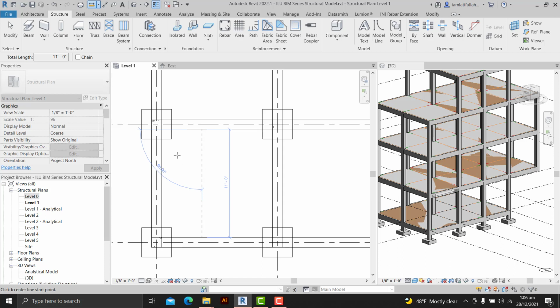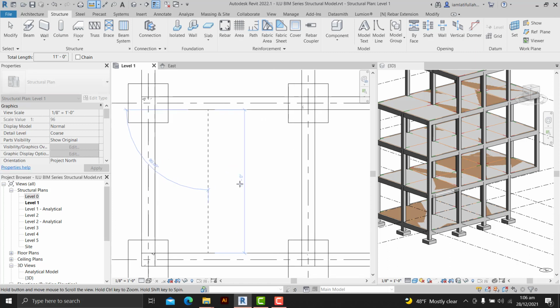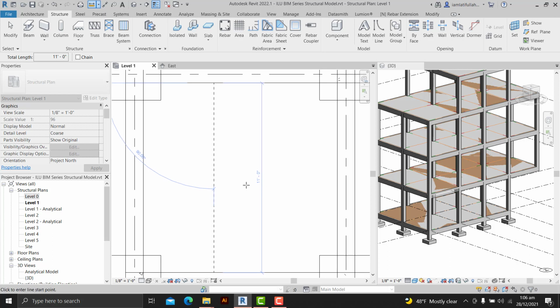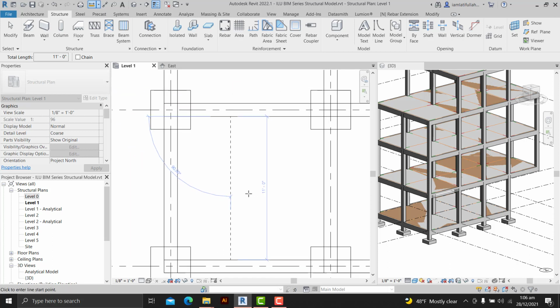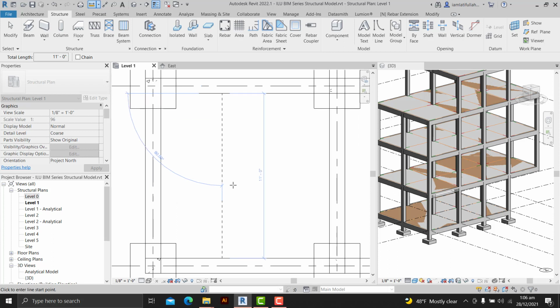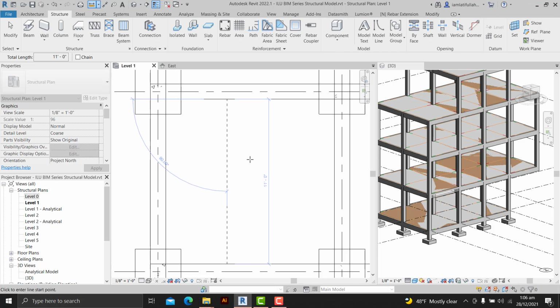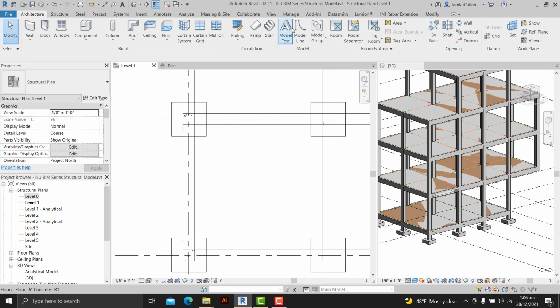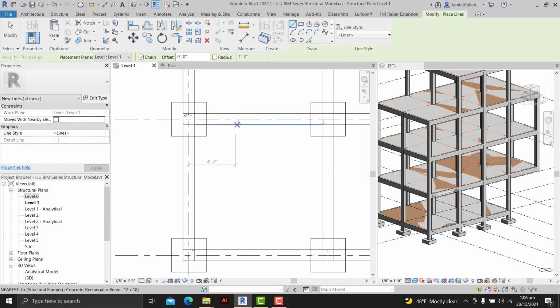So let's keep 12 stairs first here and 12 stairs here, but you see we cannot provide 12 stairs equal to 1 feet width, but we can take 10 inches for instance. So for 10 inches we would need 60 inches. So how much is 60 inch? Let's go to the architecture tab and draw our model line from here till 60 inches.